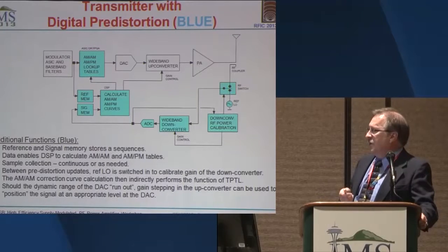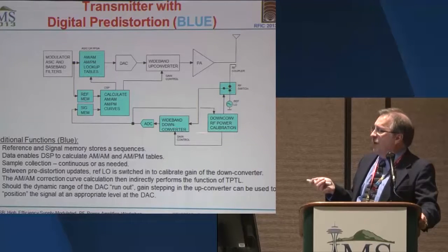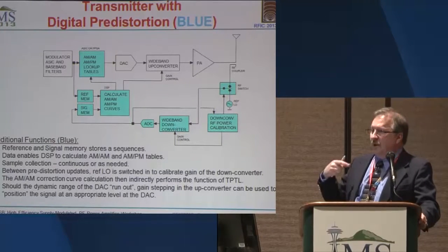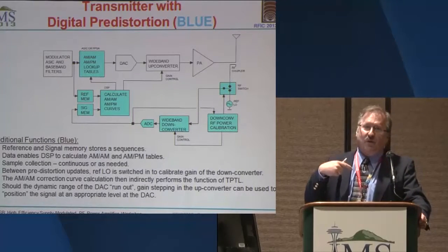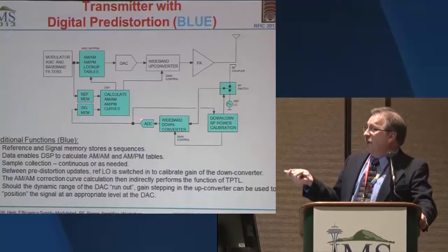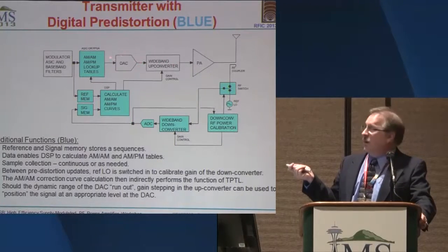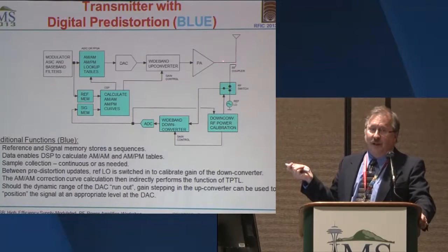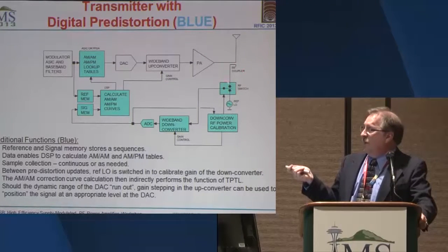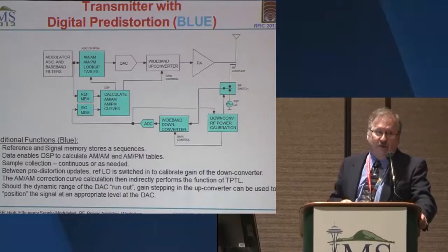up the calibration times. But the bottom line is you want to know what your receive path is on this side so that you can calibrate out any of the distortions that it's introducing. Because ultimately, if you have a clean waveform here at the ADC, that doesn't do you any good necessarily over here at the PA. That's really where you want the high quality signal, is out here at the output of the PA. So you need to, in essence, de-embed whatever this down conversion chain is doing on your feedback path.